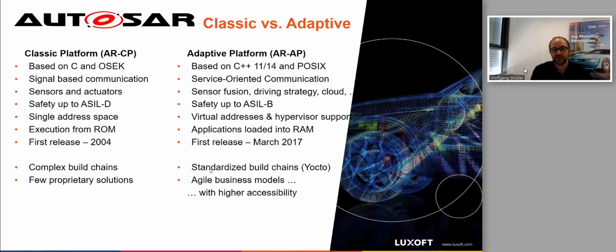In difference to Classic AUTOSAR, there were only specifications provided. The actual implementation was done by tool suppliers like Vector or Elektrobit. For AUTOSAR Adaptive, it is now different. The AUTOSAR group works also on this reference implementation. And we, as Luxoft, are contributing here as well in terms of specification as well as implementation, including the diagnostics area within Adaptive. The challenge here is now to bring these things together with the service-oriented diagnostics as described before. For the moment, this means creating service-oriented adapters for accessing the diagnostic modules of AUTOSAR Adaptive. In the long run, it should be the target to bring this service-oriented approach also into the Adaptive standard itself.